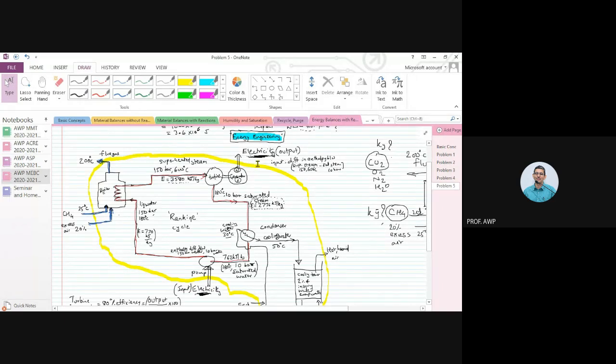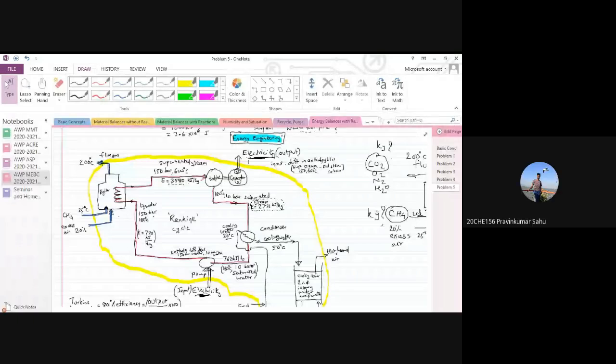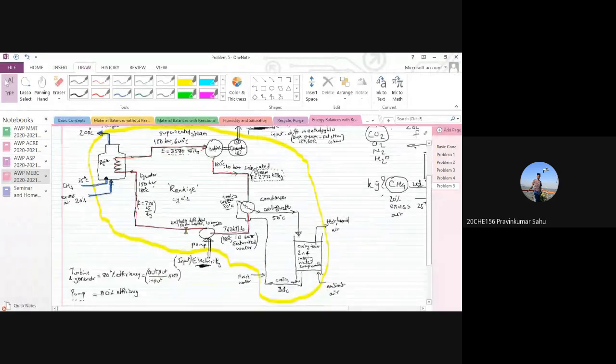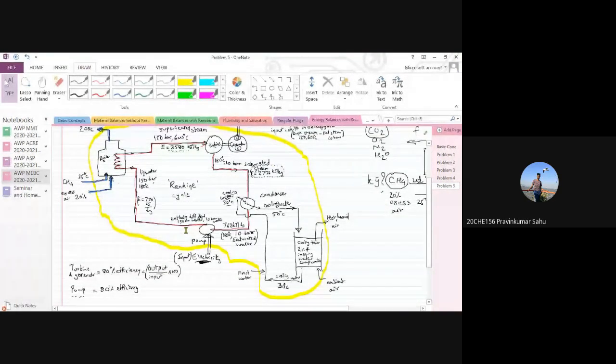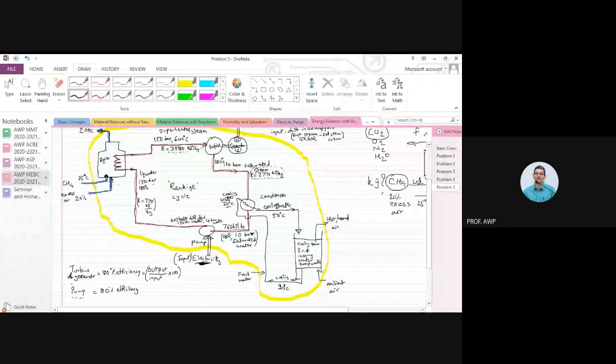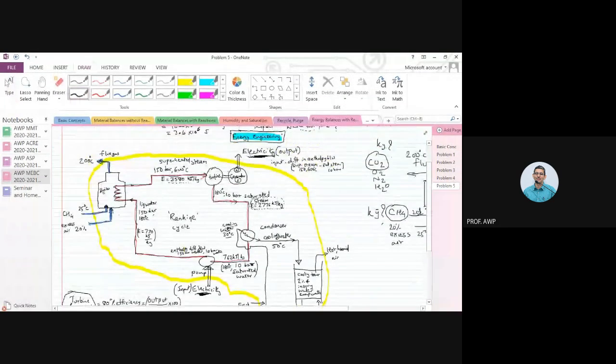Okay, so solve. Sir, I have a question. Yes, Praveen. You gave the 80% efficiency of turbine and generator. Is the 80% there separately or as a combined system? Turbine and generator put together as one system, they are combined. There are two, three other small things in between, bearings and the transmission chain. Don't worry about all of these. We are just saying turbine and generator put together is 1 unit, because they really are 1 unit. Turbine and generator are in the same housing, so to say.